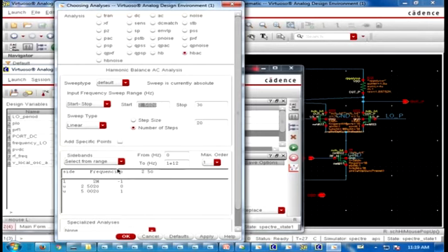And here I can select a set of ranges. So of course you can see that 2.502 is my actual RF frequency, and 2 megahertz below that is the second subband, which is actually the IF band. It is rated as -1 because it is less than 2.5 gigahertz. You can give multiple subbands, so it will come -1, -2, -3, -4 like this. This is the naming convention.